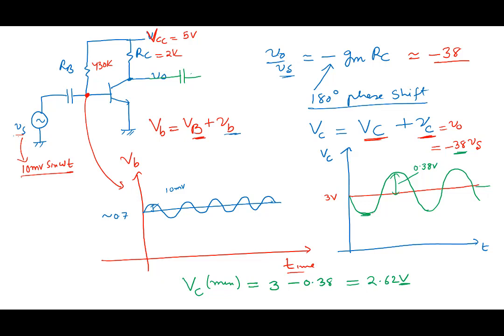No, capacitors are acting like shorts at the signal frequency. Capacitors are acting like shorts, which means they're not introducing any phase, nothing.